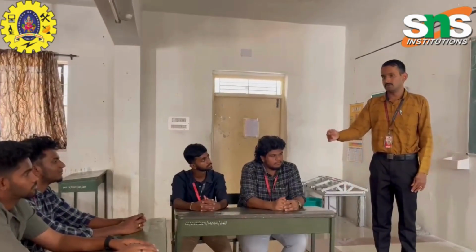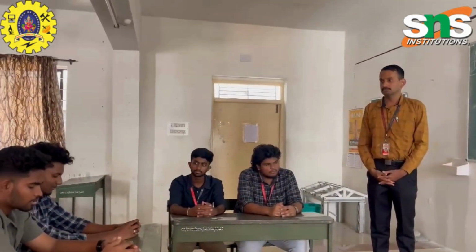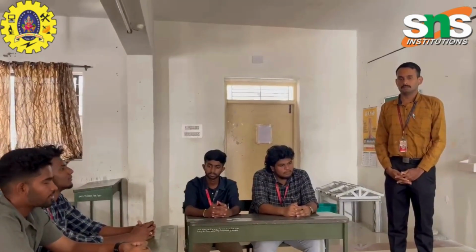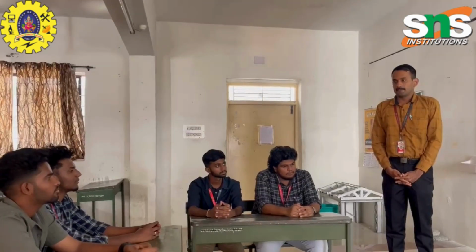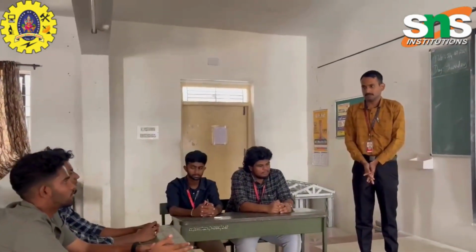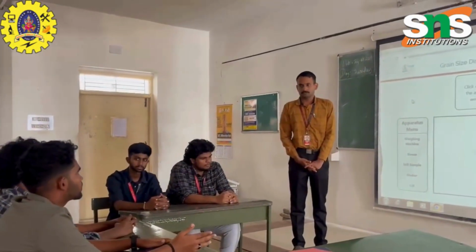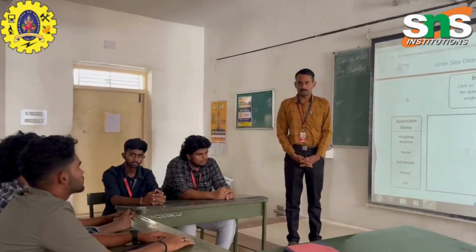Over to Sriram. For various testing, compare the gradation with the Indian Standard Code, to define the stability and propose soil improvement if required. For example, soil mixed with gravel. Soil larger than 4.75 mm is gravel. So you want to segregate the difference.